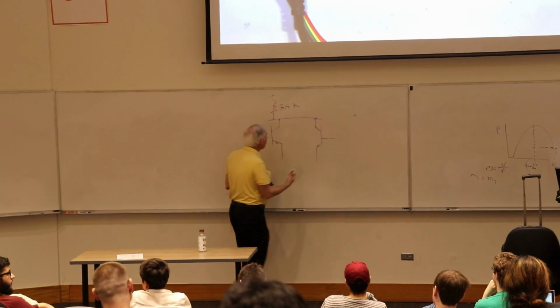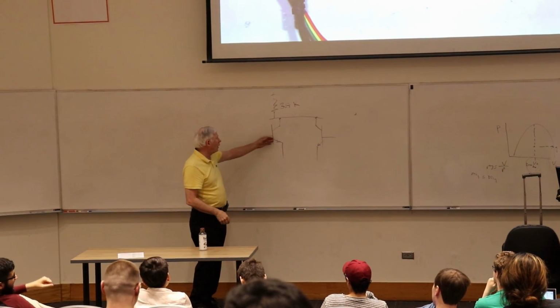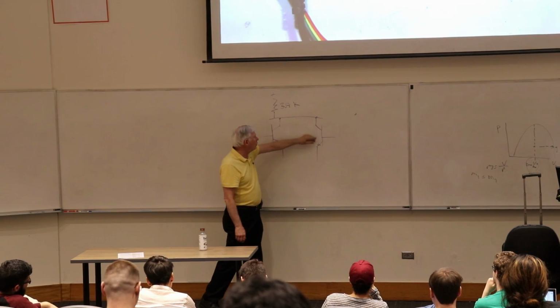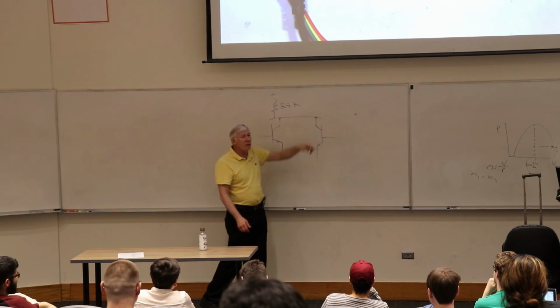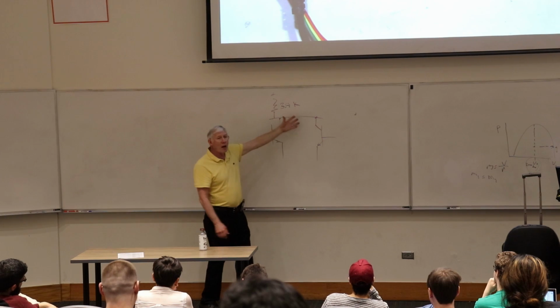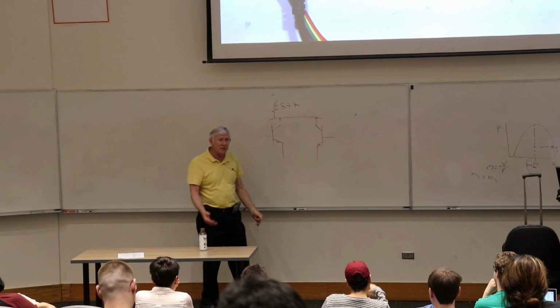And there's no way you can have a short circuit. If one device is sending a 1, then they're expecting the resistor to pull up the line. If the other device is sending a 0, they're pulling it down to 0. So this point's floating, that point's ground, and this is a 3.9K to VCC. So there's no problem, right? Everything's cool. We've got a little teeny bit of current running through the resistor, and that's it.